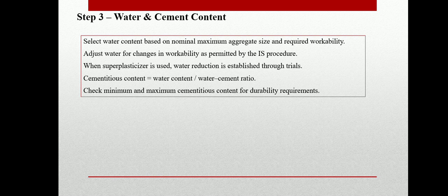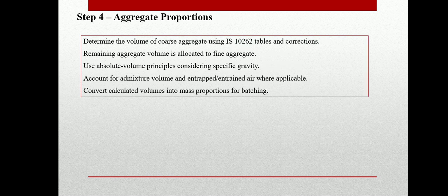We always verify that the cementitious content falls within the minimum and maximum limit specified for durability requirements. Too little cement compromises durability. Too much cement can lead to other issues like excessive heat of hydration or shrinkage. So next is about aggregate proportion.